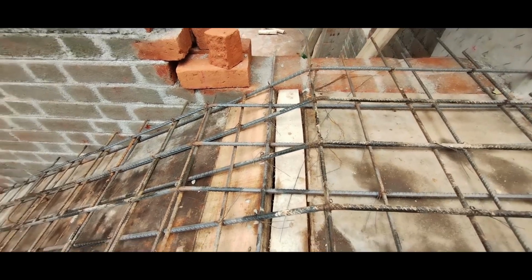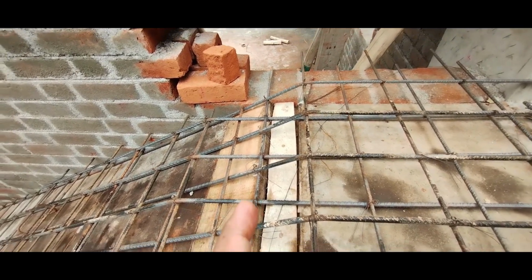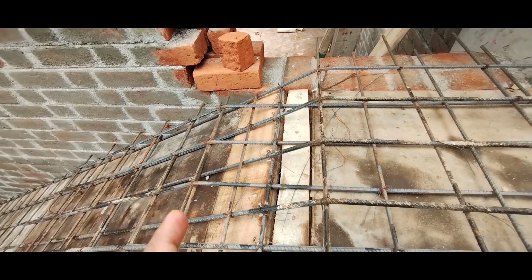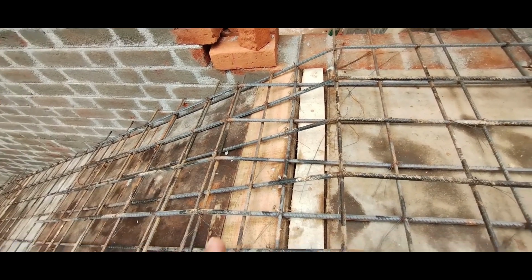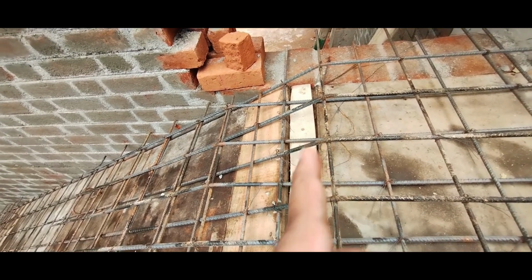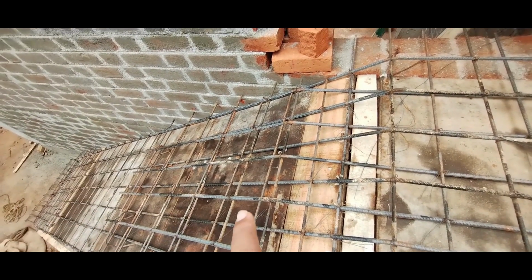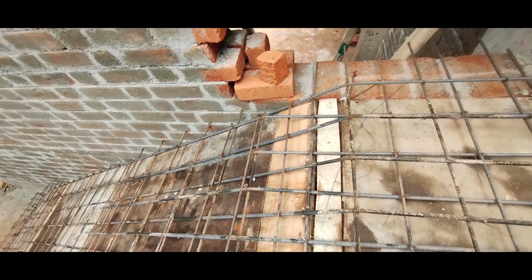The bottom part, just follow this beam. Just follow this rebar. See, it's coming from the top, and it becomes the bottom part over here. And the same thing over here. This is the bottom part, it comes and becomes the top part. So alternately this has been done. Whatever is at the top over there comes and becomes the bottom, and whatever is at the bottom comes and becomes the top part.